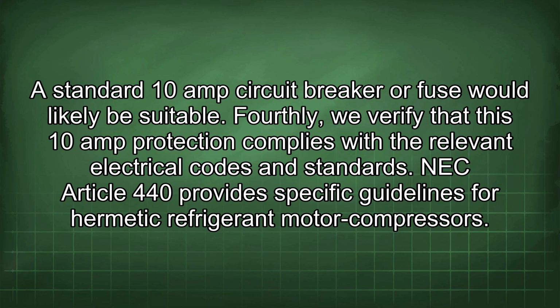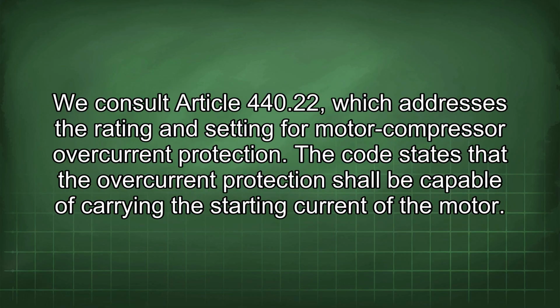Fourthly, we verify that this 10 amp protection complies with the relevant electrical codes and standards. NEC Article 440 provides specific guidelines for hermetic refrigerant motor compressors. We consult Article 440.22, which addresses the rating and setting for motor compressor overcurrent protection. The code states that the overcurrent protection shall be capable of carrying the starting current of the motor.